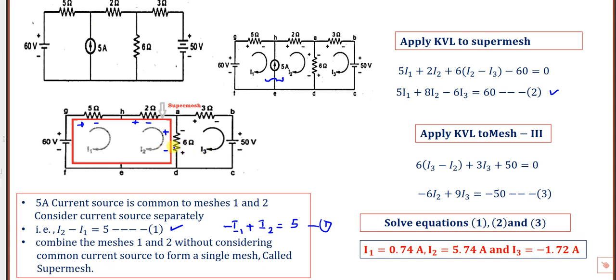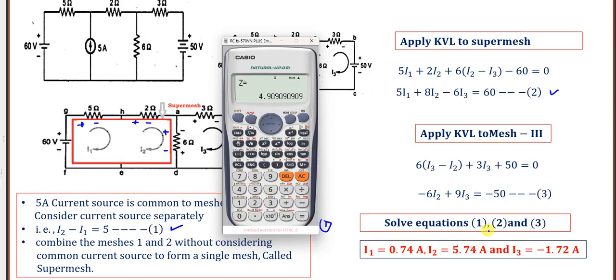So I3 minus I2. The 3 ohms is at the edge, so only one current, I3: 3 I3. Then plus 2 minus plus 50 is equal to 0. After simplification, minus 6I2, 6I3 plus 3I3 is 9I3, and this plus 50 brought to the right side becomes minus 50. So we got three equations. Now I can solve the three equations using a calculator.